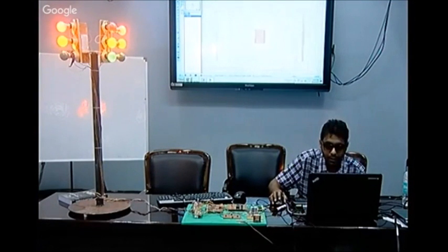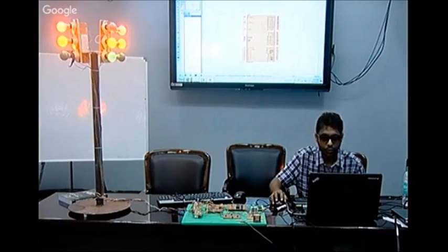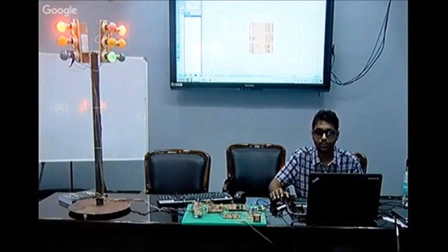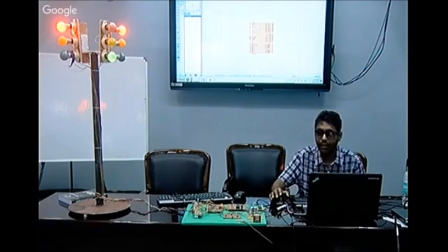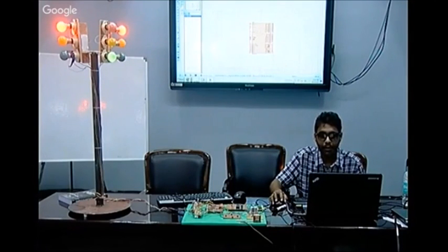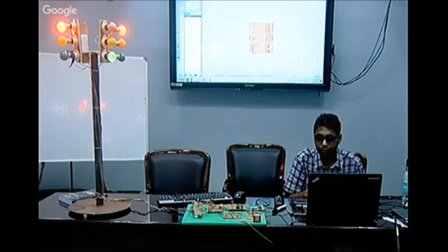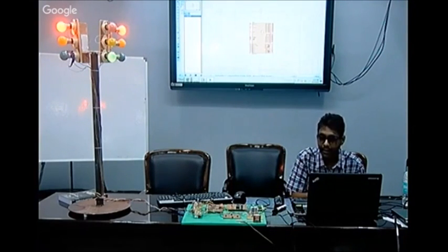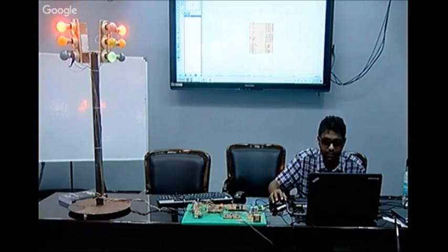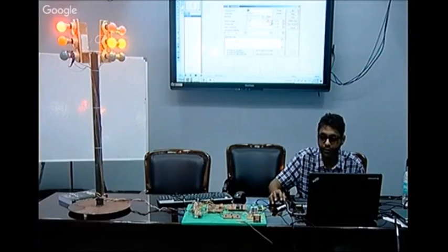After selecting the component, the main component is this microcontroller. Every component has some parameters or properties that we have to set while simulation. The main property of the microcontroller is the operating frequency and the text file it needs. So these are two parameters. Just right click on the component and a dialog box will appear. These are the properties for the 8051 IC.